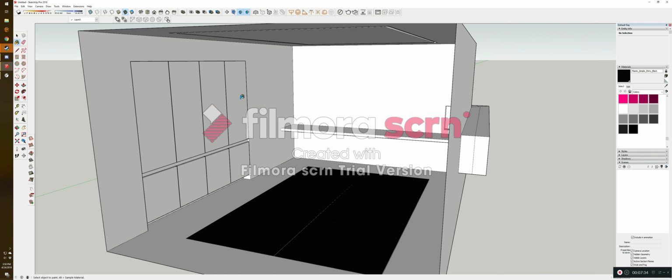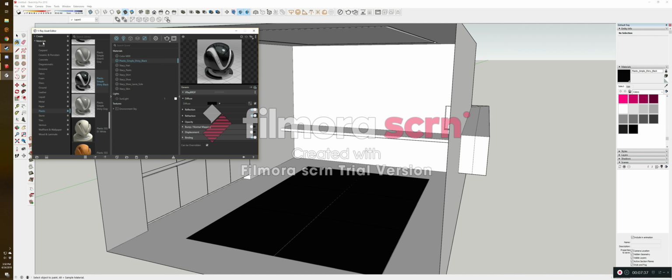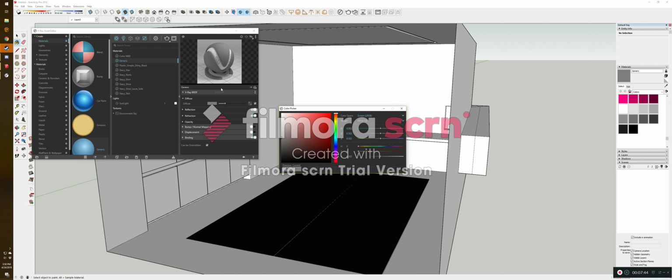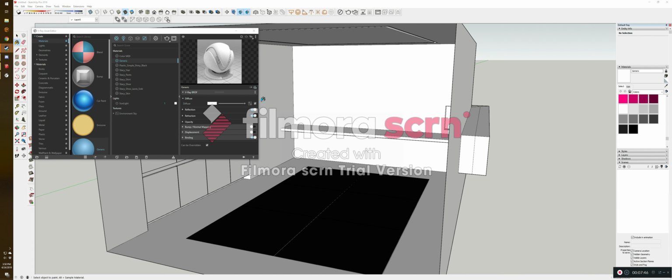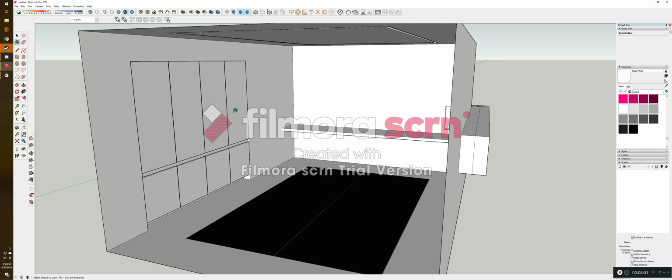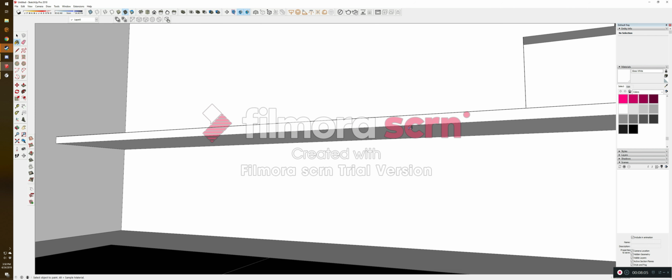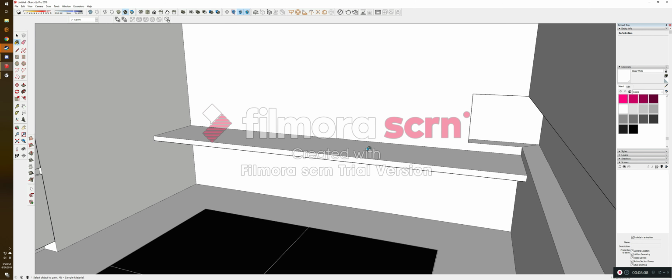Now we also want, I'm going to have some glossy here, but these are going to be white so that it matches the wall, so I need to create that material. So for that we're going to go into Create, Materials, and grab a generic one. Change the color to white. We're going to bump the reflection up, turn the IOR on, and rename it Gloss White. My gloss white selected. We're also going to do the table in gloss white.